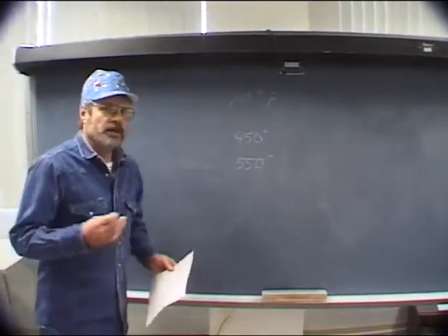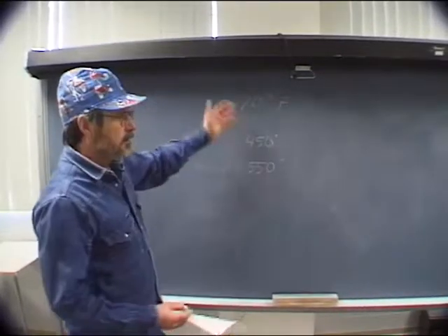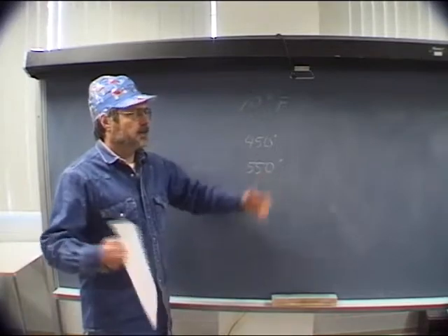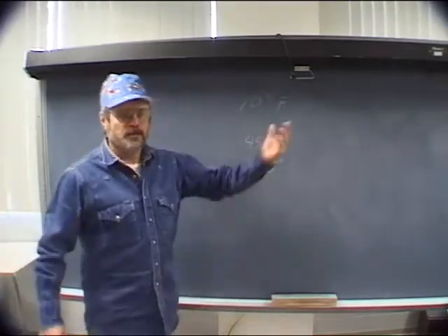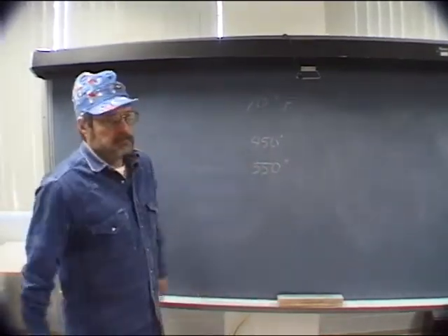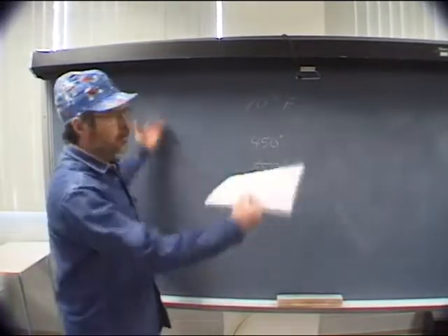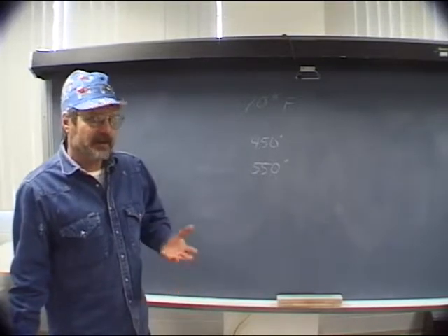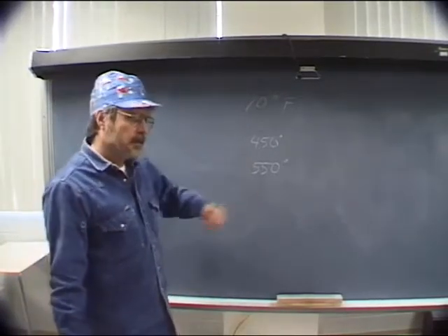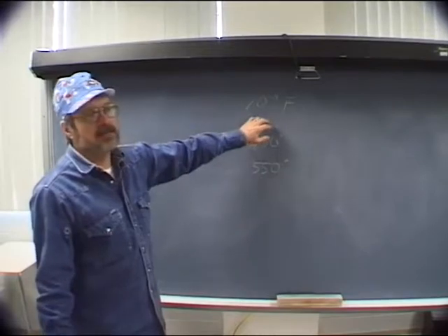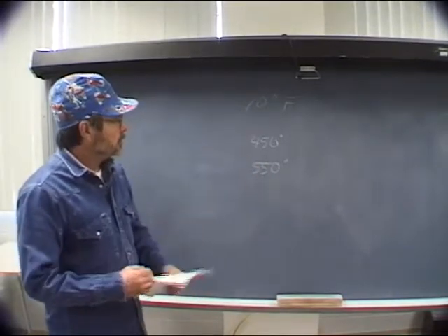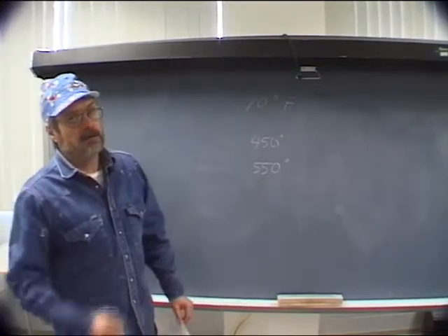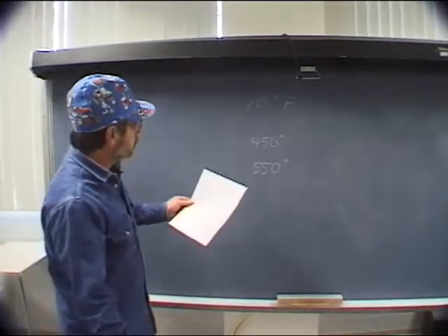However, there is such a thing called interrupted welding. Let's say a guy's out here making a production weld on pipe, the way we've been discussing, and it comes to lunchtime and he breaks, goes in, eats, and comes back an hour later, and it's 20 degrees outside. Of course, everything's cooled off and gone down. As an inspector, it's kind of tough, but you have to try to get out there and make sure that he preheats it all back up again to at least that 70 degrees. That would be called interrupted welding, and sometimes, under some codes, interrupted welding is not allowed. So again, you've got to know your codes.